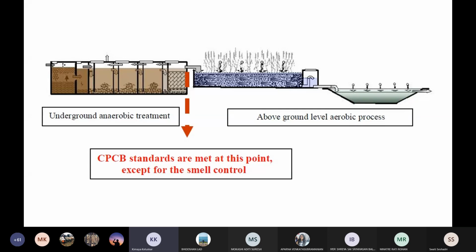So it's an underground thing. You don't see them. You only see those top manholes, which are accesses to maintain these things and remove the sludge when it reaches its capacity. This is totally underground. It's only 450 mm above ground so that the storm water or surface runoff in the monsoon doesn't get into these tanks and contaminate them. Clear? Understood up to the red line?